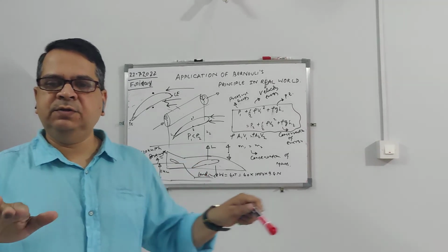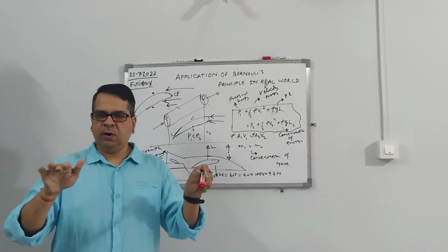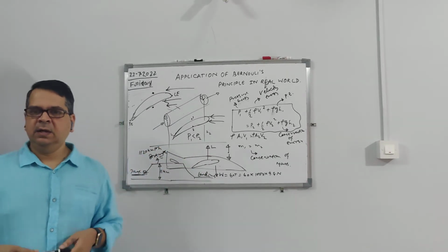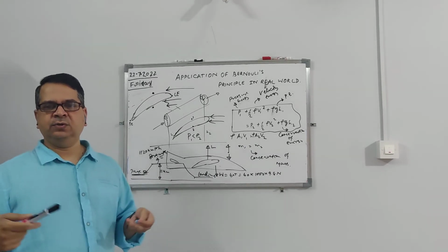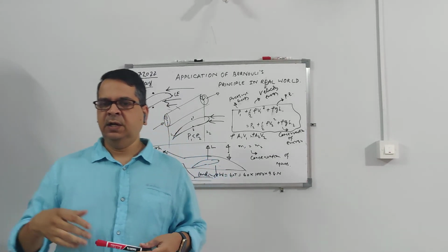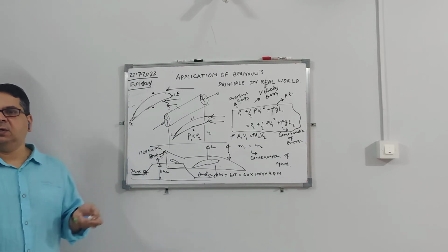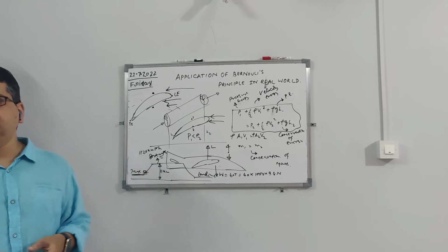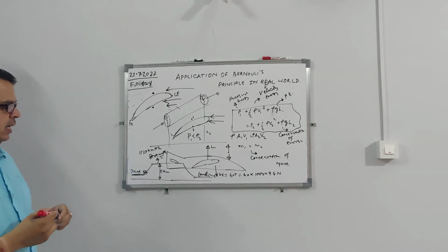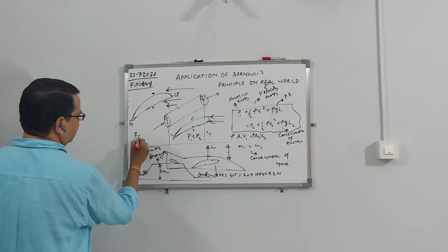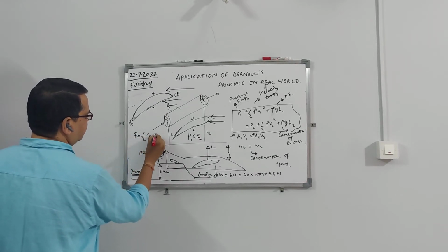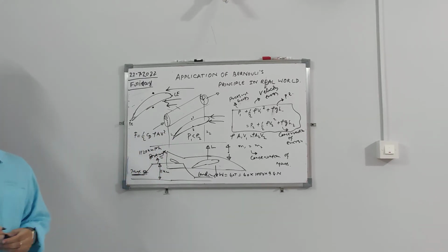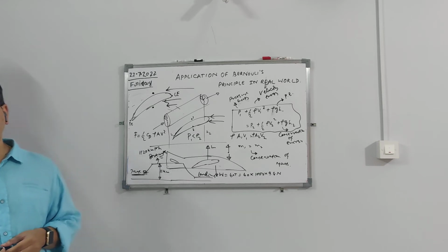Your aircraft is moving forward, right? When it is moving forward, there is viscosity, which we have studied. Viscosity is nothing but friction. In fluid flow, this viscosity causes friction, so there will be a frictional force. That is called the drag. The faster you move through the air, the more is the drag. That drag force has a formula: half CD rho A V square. CD is called your drag coefficient, like your coefficient of friction.